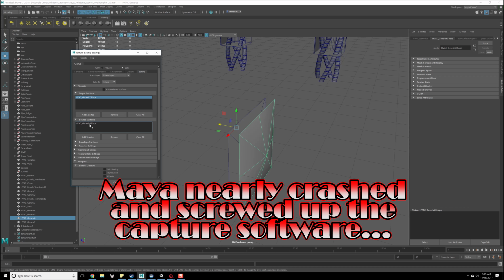What do I want? Normal map. Let's just give it a shot and see what happens. So I'm going to click, I believe this one. This is texture bake. All right, this is not working, so let's stop this calculation. I think the problem is I don't have hard edges, so let's change that. Let's grab this and go to mesh display, and do hard edge. Now let's try that baking again. There we go. That is exactly the normal map I want.